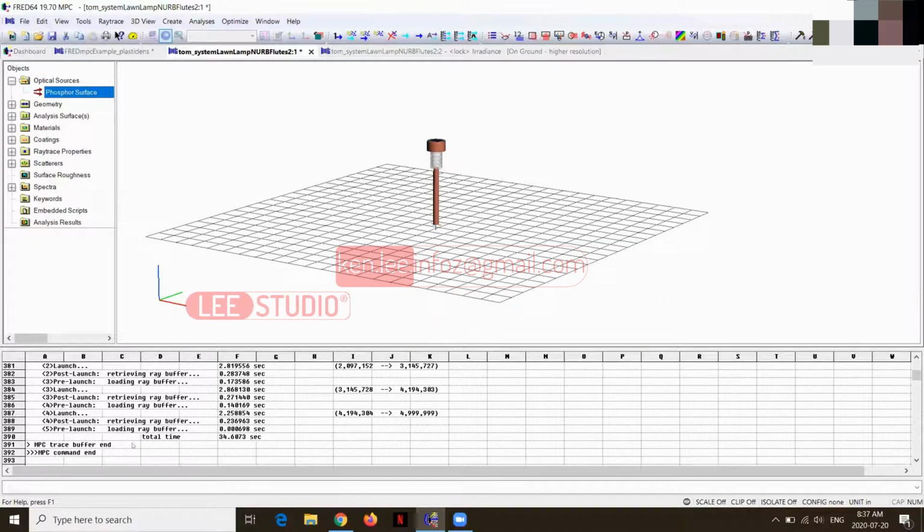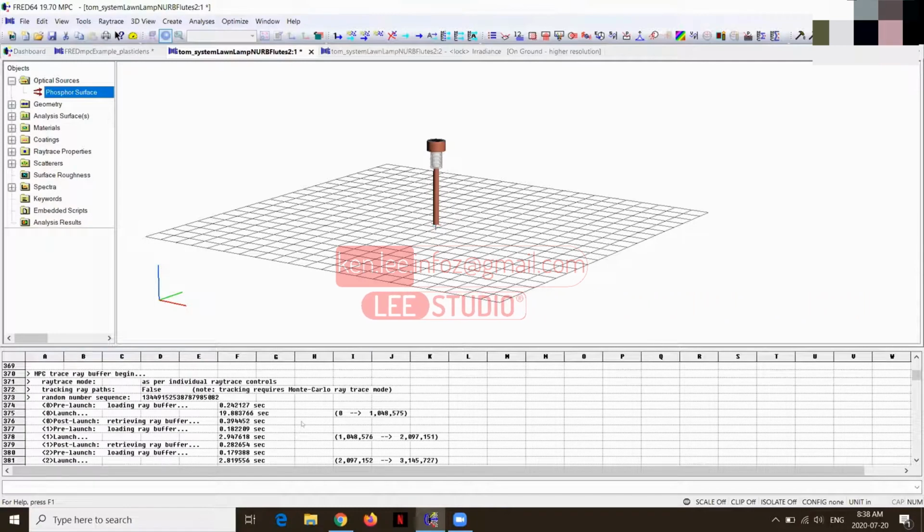And the same if you bring all the rays back to the CPU to do post-processing, scripting, or something like that. Again, it becomes slower if it has to go to the virtual memory on the hard disk. That's another advantage of using the GPUs for ray tracing: because it traces rays in batches of 1 million rays, you don't run out of memory. So there's never any slowdown depending on how many rays you're tracing.